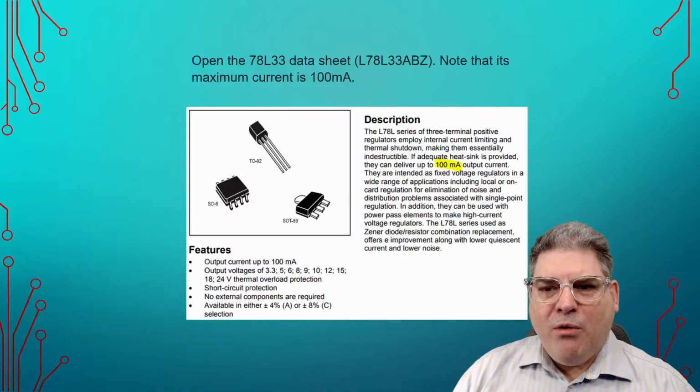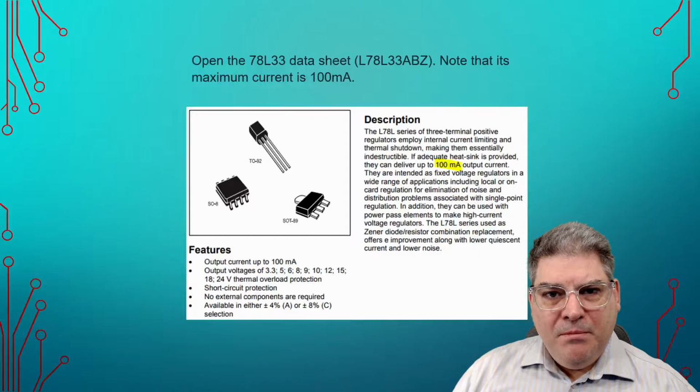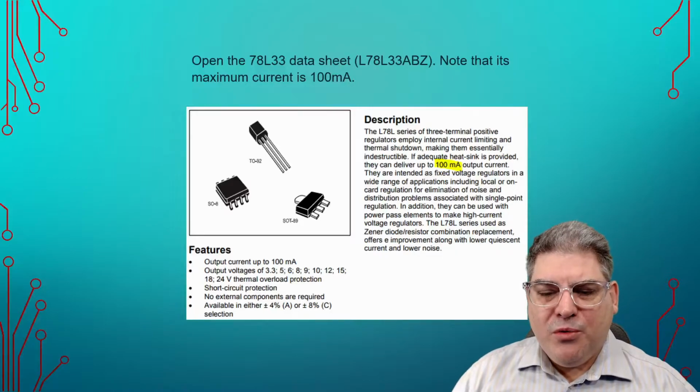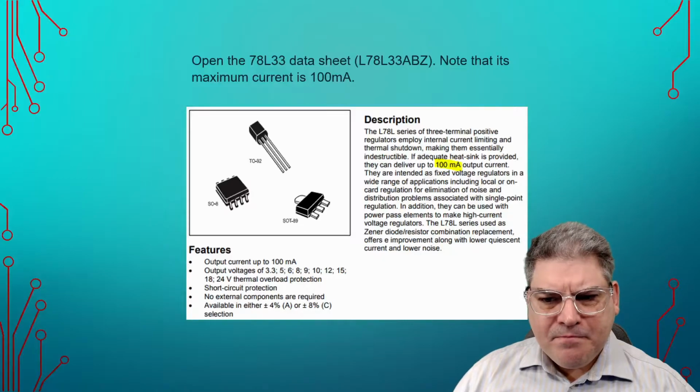And so, for example, if I was taking 10 volts at 10 milliamps and I wanted to output 5 volts at 5 milliamps, then I would have 5 volts being dropped at 10 milliamps. It gives me 50 milliwatts just simply by multiplying the two numbers. And 50 milliwatts on a package like this isn't too bad.